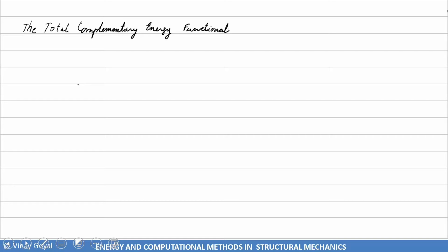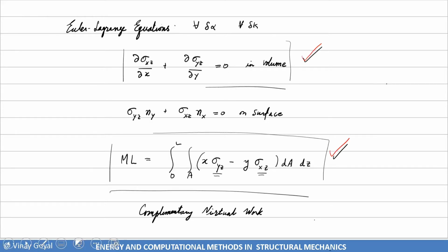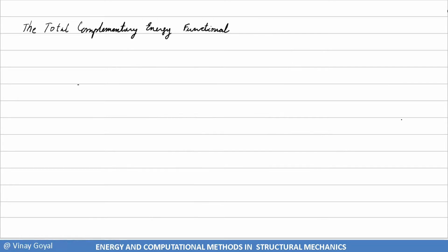And the benefit here is that perhaps we can come up with an approach that can allow us to get there quicker. Now, we know from the Euler-Lagrange equations that we have to satisfy this equation. And so that's the equation I have to satisfy. So let's look at that equation again. I'm going to say, well, that is an equation I want to satisfy. So can I come up with a stress function of some kind that satisfies that automatically?